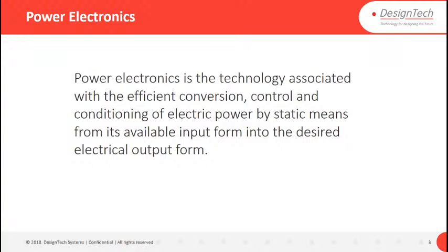And if you see, there are always some fluctuations in electricity. Sometimes voltage is low, sometimes voltage is high. If you use that power directly in any electronic device, or an AC, or a refrigerator, some kind of noise will be generated, like common mode or differential mode noise. And once noise is generated, your system can shut down or break down. So it is very important to design a converter to get a constant voltage at all times.